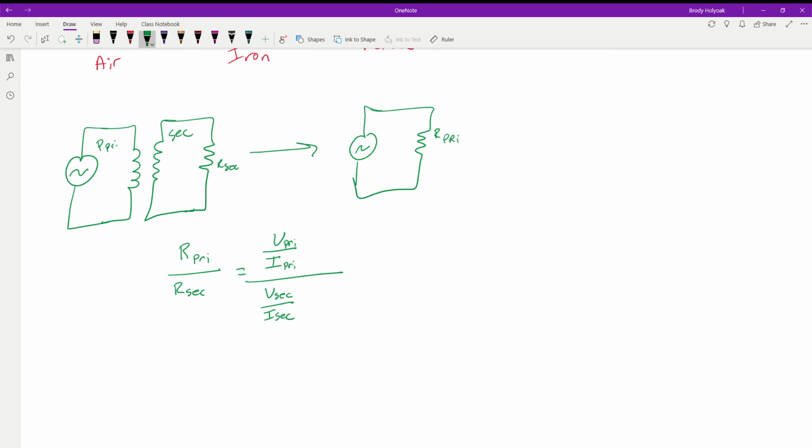The reason we're going through this is to see that we can solve for these things without having to go through the entire circuit. We could have our transformer, several resistors, a couple capacitors, inductors, whatever it is. We could just run through this formula to determine what this source is going to see against everything. Like I said, this will all simplify out in just a second. We'll use this once in a while to understand quickly what my source is seeing, what kind of a load I am putting on this source, so we can use it to impedance match.